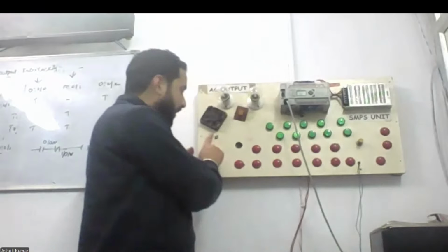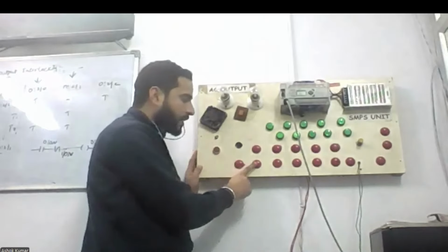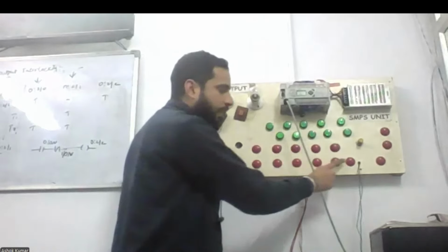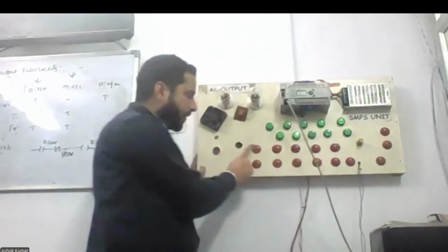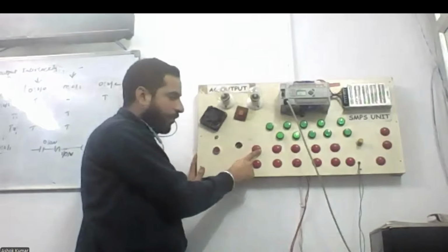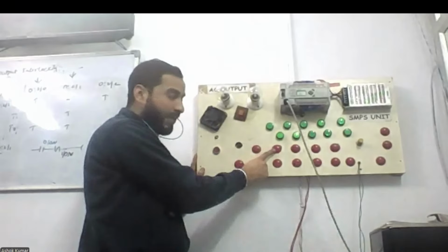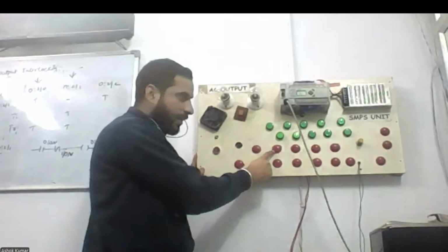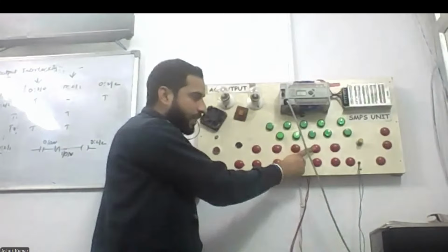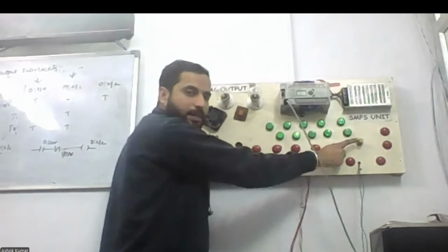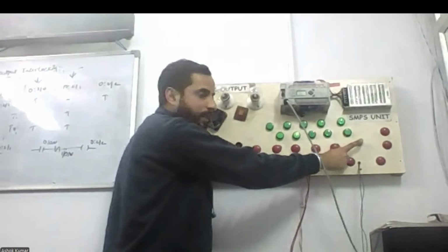So let's start it again. I colon 0.0 slash 0, slash 1, slash 2, slash 3, slash 4, 5, 6, 7, 8, 9, 10, 11, 12, and then from here 13, 14, 15. 15 is the last bit, right? So now we need to change the word address. So the address would be I colon 0.1 slash 0, 1 slash 1, 1 slash 2, and 1 slash 3. This one is the proximity sensor, right?